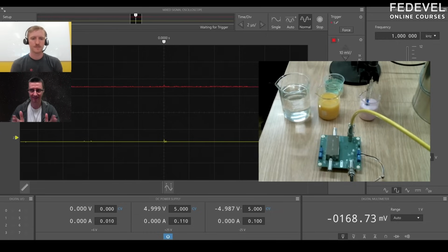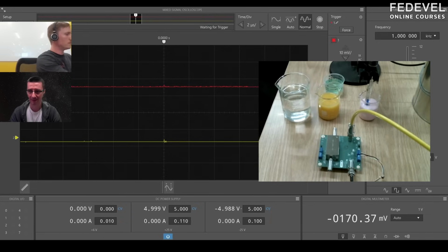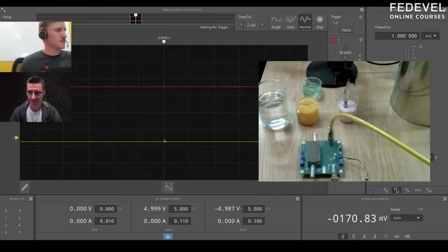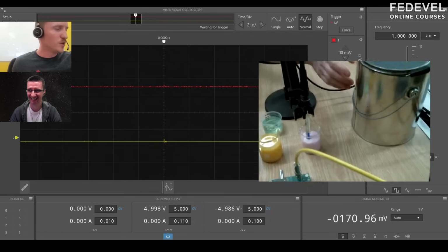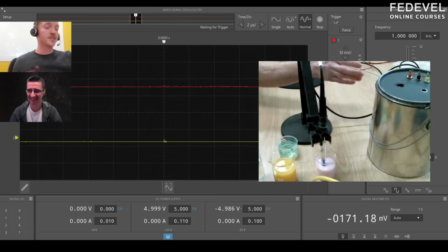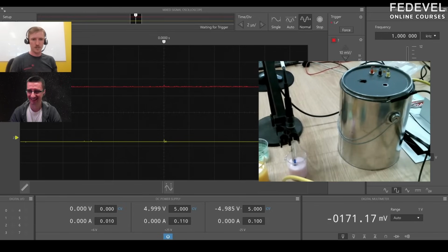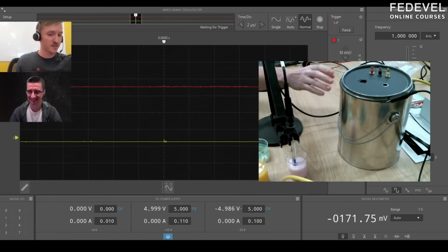Cool. And this is the reason why we need to know how to actually design op-amp circuits properly, because, for this specific application, if it's not done properly, then it's not going to work. That's right. And I'll give you one good example of that. I don't know if you can see in the camera, but with this demo, we have a little bit of exposed wiring where we were connecting it together. And of course, we had to place it in this tin can here, which is connected to the analog ground of our circuit, and that's to shield those cables from any kind of interference.